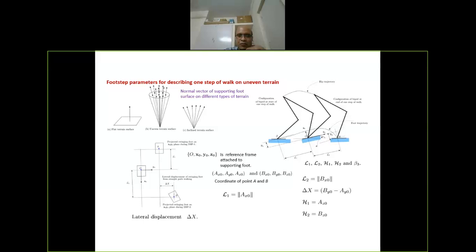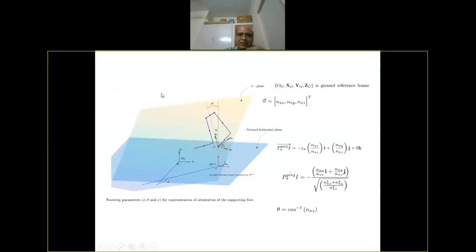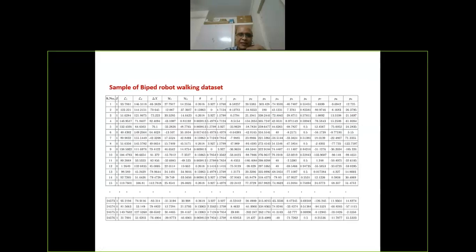So when the robot is going upward, the normal vector, which is going to be on the foot, can lie anywhere in this cone, which is the friction cone. Okay. So basically, we optimize this, and then for each of these, we find the corresponding trajectory. Okay. So now this is an example of the data set which is created.